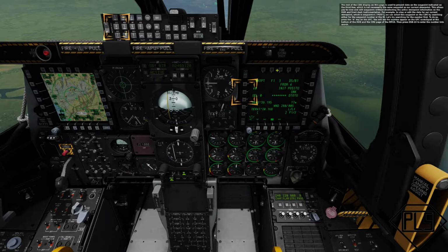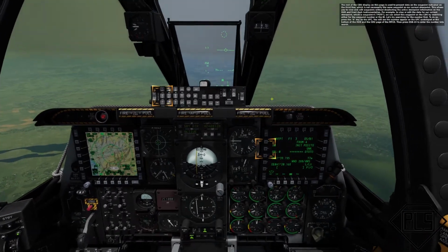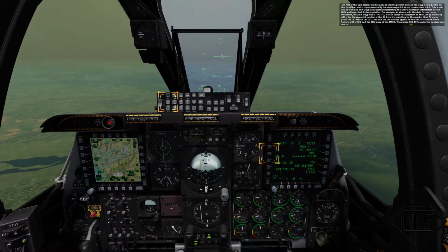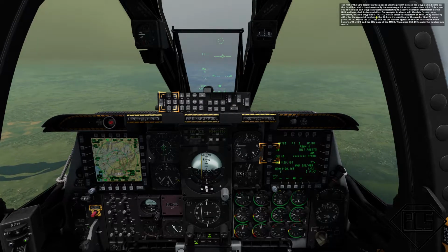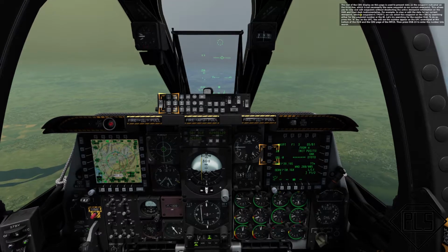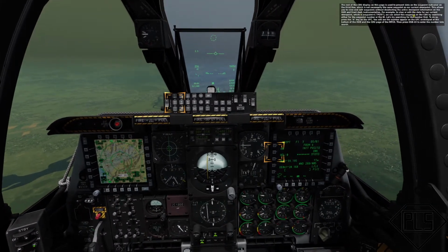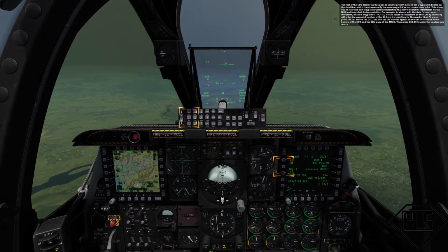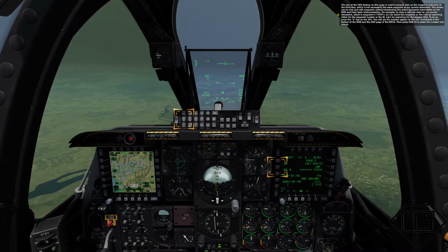The rest of the CDU display on this page is used to present data on the waypoint indicated on the third line, which is not necessarily the same waypoint as our current steer point. This allows you to view and edit waypoints without deselecting the active steer point information on the HUD and front dash instrumentation. For example, to view or edit the data for our current steer point, which is waypoint 4 Pote, we can select this waypoint on the CDU by searching either for the waypoint number or the ID.